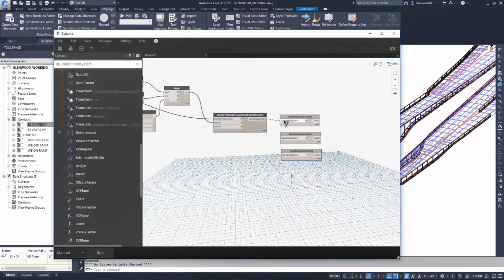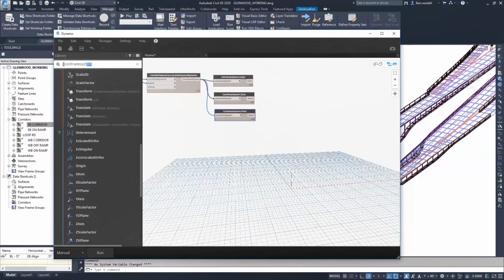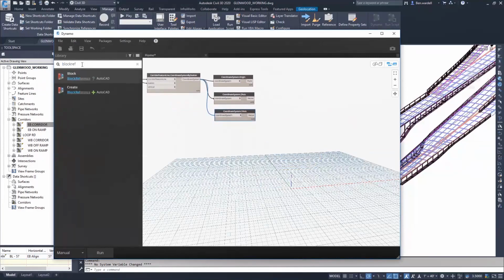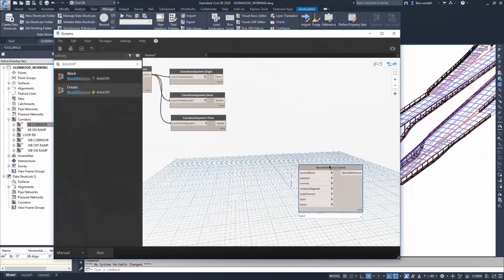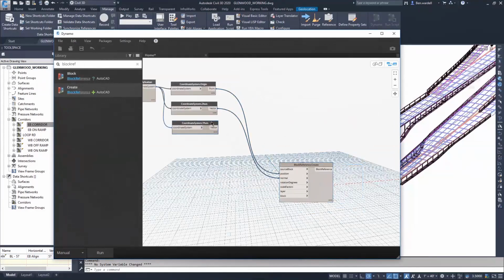That is in terms of Z, because it's also going to be a 3D model within the corridor that you are placing. That's why you need to choose the coordinate, and the coordinate must also correspond to the specific orientation based on the model that you are having. Remember that we all know Civil 3D models are georeferenced, therefore you must have selected the correct coordinate for use within the Civil 3D models. Just allow it to automatically read the coordinate for the Z, the Y, and the X that has been used for georeferencing of the Civil 3D model. This script that you are creating is something you can reuse later.